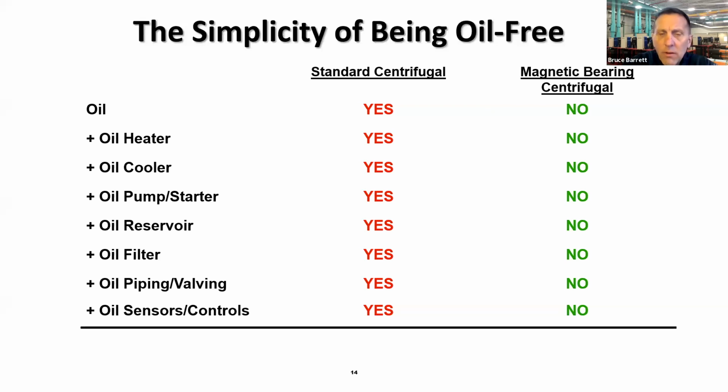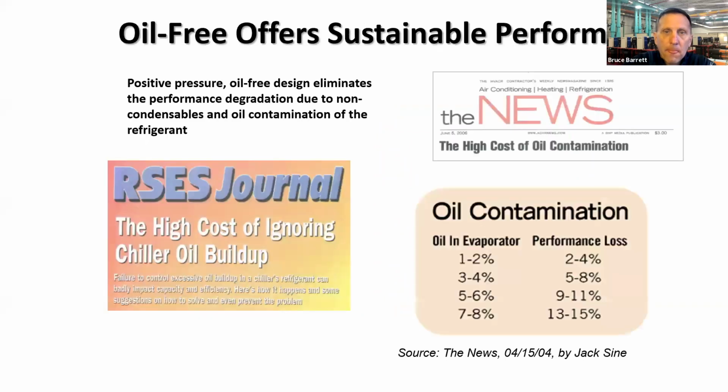When you've got oil-free compressors, you don't need a heater, a cooler, a pump, a reservoir, a filter, piping valves, etc. These are refrigerant-cooled, suction gas-cooled compressors. The drive still needs to be cooled off, but we don't use oil or water to do so. That is a differentiator between some other manufacturers that use condenser water and those associated maintenances required with it.